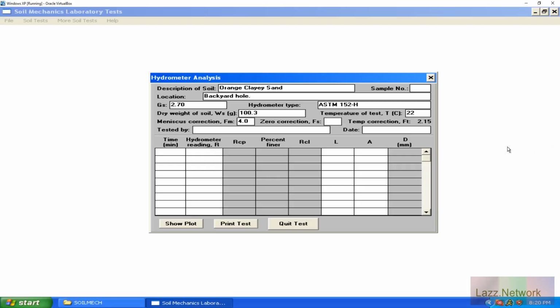So you also have a zero correction. Your zero correction, I think that might have to be a negative number. I don't know. I know in Geosystems it's a negative number. I guess we'll see when I put in all the data. So for this one, I should be able to put 0.0 or just 0. Over time your hydrometer might get worn out, where you might have to recorrect where your zero mark is going to be.